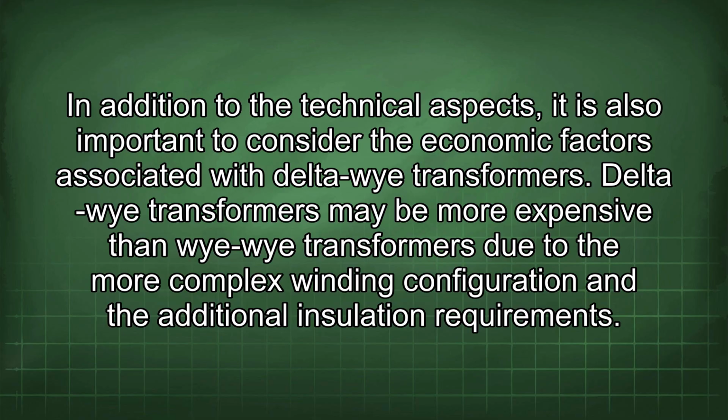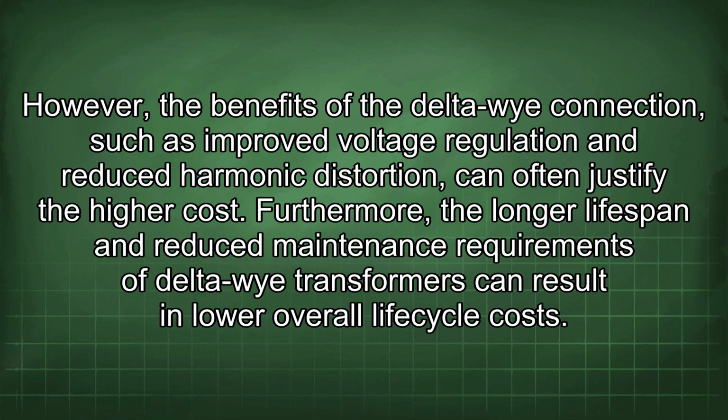In addition to the technical aspects, it is also important to consider the economic factors associated with Delta-Wye transformers. Delta-Wye transformers may be more expensive than Wye-Wye transformers due to the more complex winding configuration and the additional insulation requirements. However, the benefits of the Delta-Wye connection, such as improved voltage regulation and reduced harmonic distortion, can often justify the higher cost.